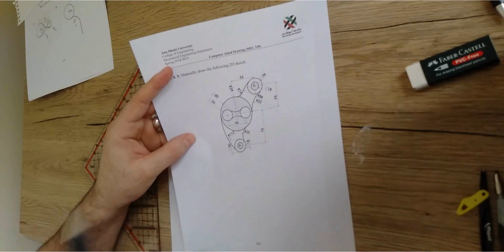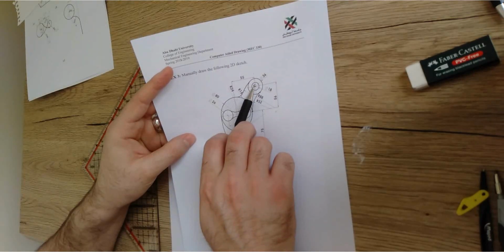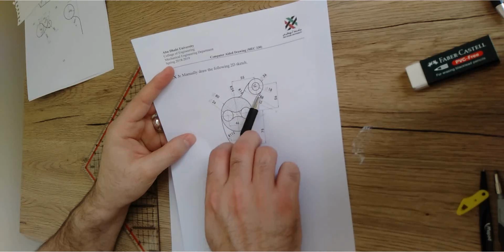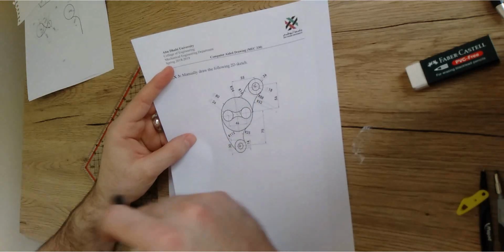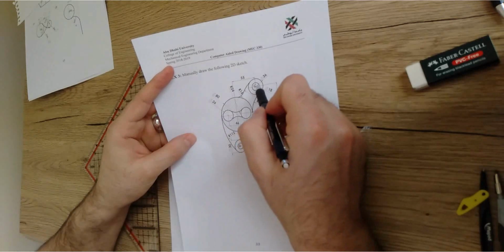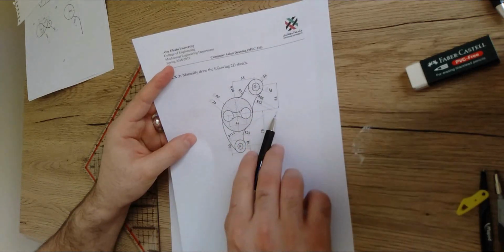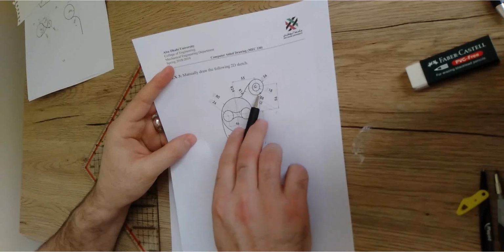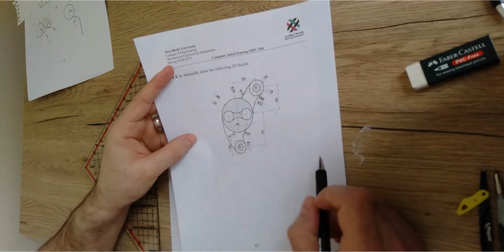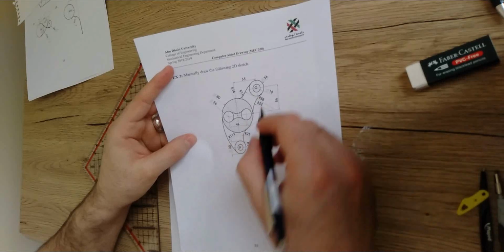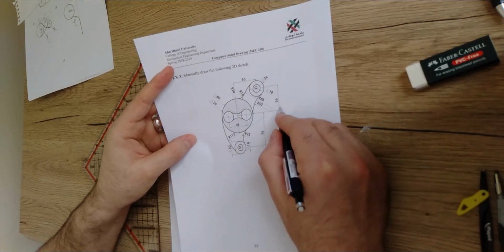Then if I ask you to move from the center to the center of this circle, are we gonna go over the tangent point? Yes, we do. So what does it mean? It means that we have to add the radius of this circle plus the radius of the curve to end up with a locus here, right? So the radius of the curve is 52 plus the radius of this circle, which is 18. This gives in total 70, right? So it means that we're gonna fix from here and open the compass with 70 and draw one locus.